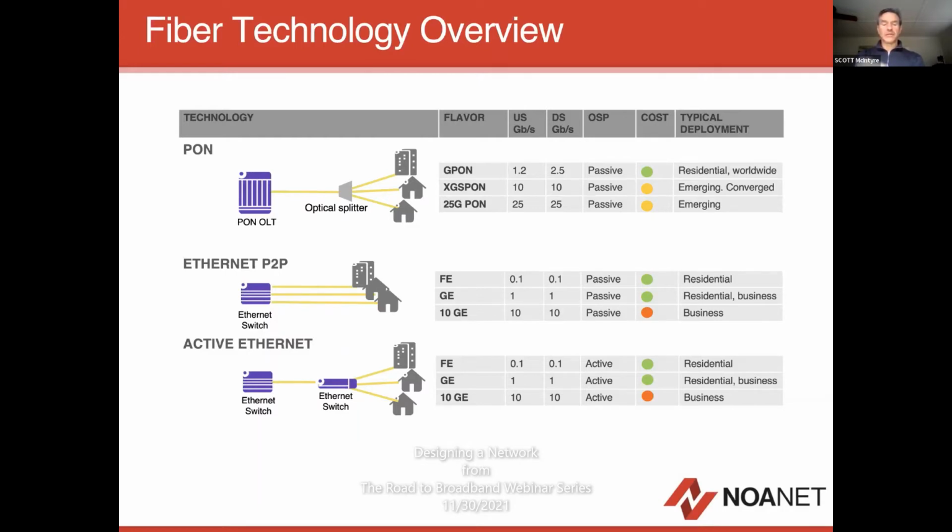The DC rectifier and the battery plant and the Ethernet are going to generate heat. And so you're typically, in most of Washington, going to have an air conditioning unit on there. All of those things actually cost money to run, and all of those things also are going to have a maintenance life associated with them that will eventually result in a truck roll to either replace them or maintain them. Thanks, Scott. Any other questions or go on?